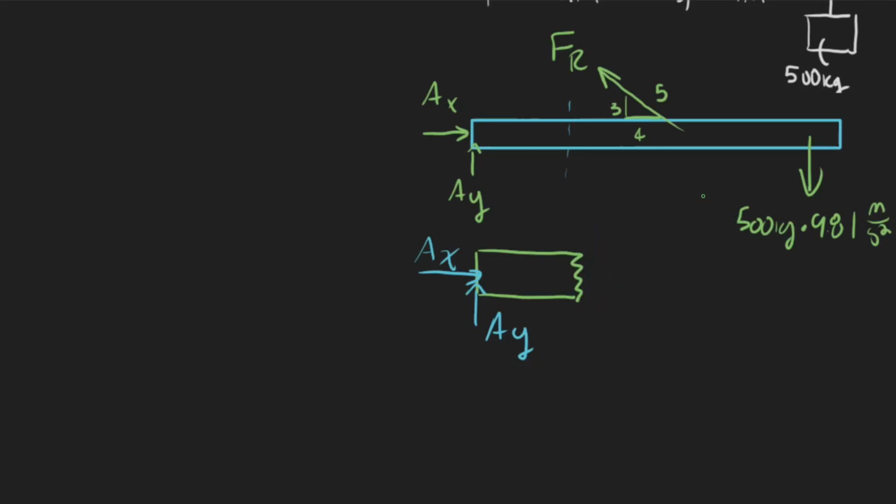And our convention for this is to break it into the components. So we say that basically perpendicular or normal to this cut, we have the normal component of the force, and the shear force is always clockwise. So in this case, it would be down on the right side or up on the left side. So we'd have our shear right here, and then the moment causes it to bend up. That's our positive convention. So the moment would be here in this case.